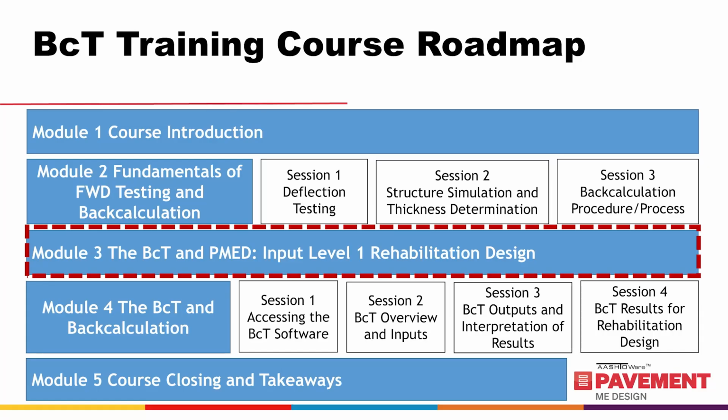In Module 2, we've discussed the fundamentals of deflection testing procedure using FWD, how the back calculation is performed, simulating pavement layers with estimated thicknesses using GPR or coring. In this module, we'll take our discussion one step further by demonstrating how different pieces of information obtained from the back calculation procedure is used during pavement rehabilitation design by PMED.